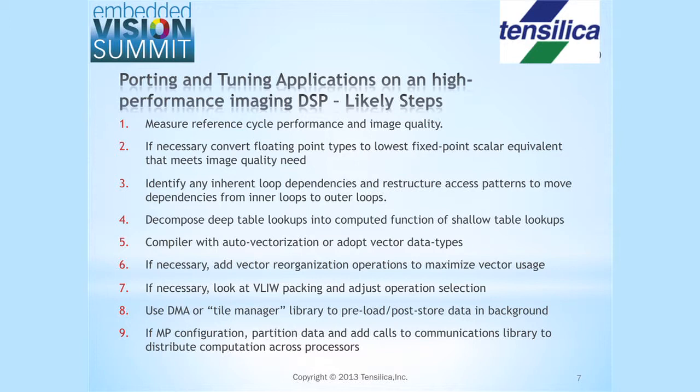Rather late in this process, you get to start to look at things like how efficiently the parallel issue works in your machine, be it VLIW or dynamic superscalar. This is typically handled pretty well by the compiler, and so only in the most extreme tuning do you have some choices about operation selection that can interact with the VLIW packing.